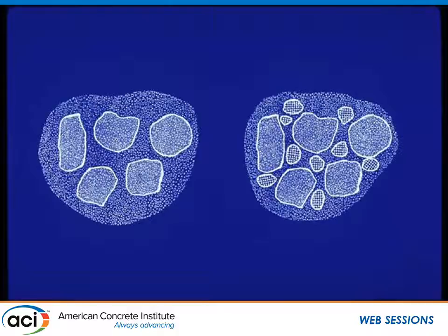And when we use the other cementitious materials of the other sizes, instead of, on the left, where we have the 5 cement grains fit in that one space with some gaps in between them, we can pack little pieces of fly ash, slag, silica fume in between those cement grains. Now when these cement grains are trying to spread out their fingers to reach and connect into the next grains, they have to span a larger space when it's just cement grains, so they have to span a much smaller space when we have those smaller materials stacked in between.